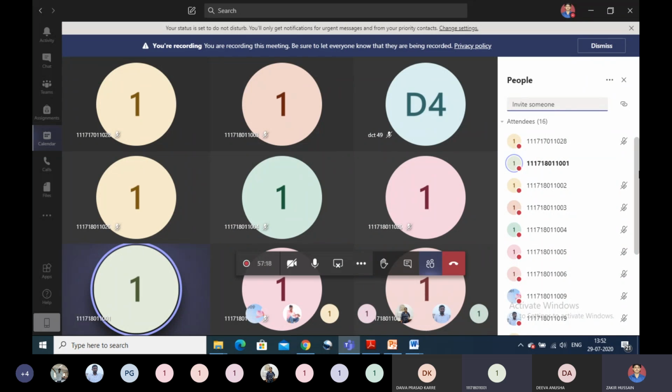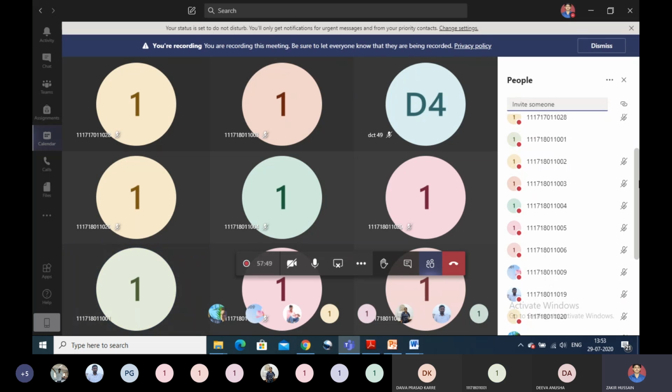And what is Fick's first law of diffusion? N of A is equal to minus D_AB dou C_A by dou Z. Not N_A, it is J_A. N_A is a separate relationship; there is a relationship between J_A and N_A, known as the relationship between fluxes. You just go through the notes. Okay, sir. Number 2.